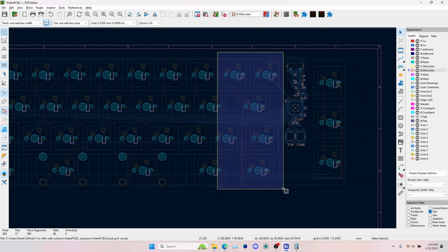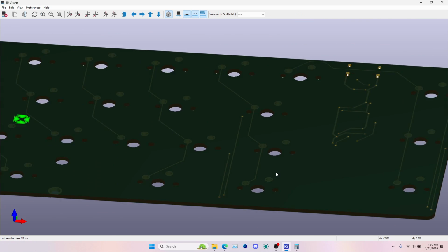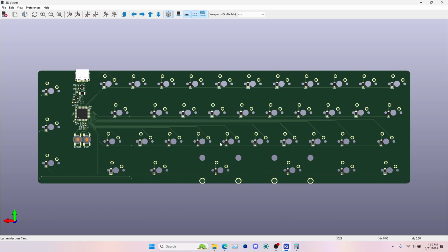We don't really care which diode is which, because they're all identical. And we all know that all the diodes are going to be between switches, and there aren't diodes anywhere else. So there's really no point in referencing that on the PCB itself. This also gives it a much cleaner look, in my opinion, in the 3D view, without all the random text being cut off by holes.